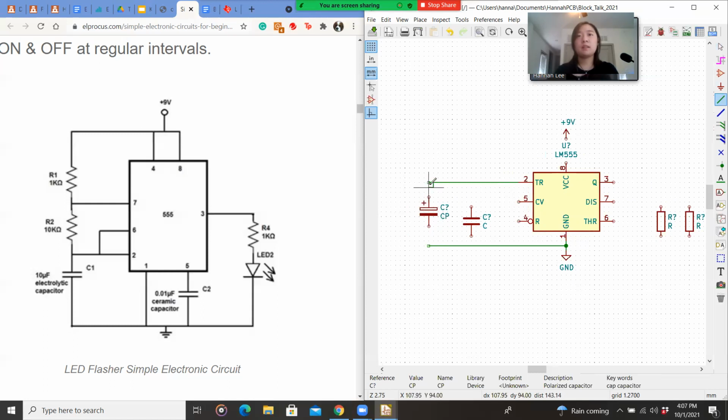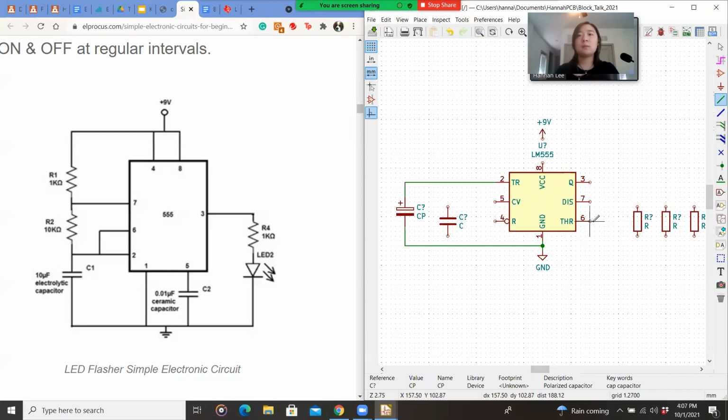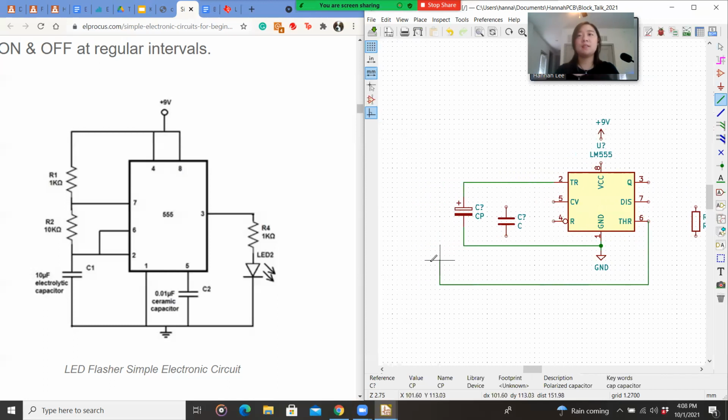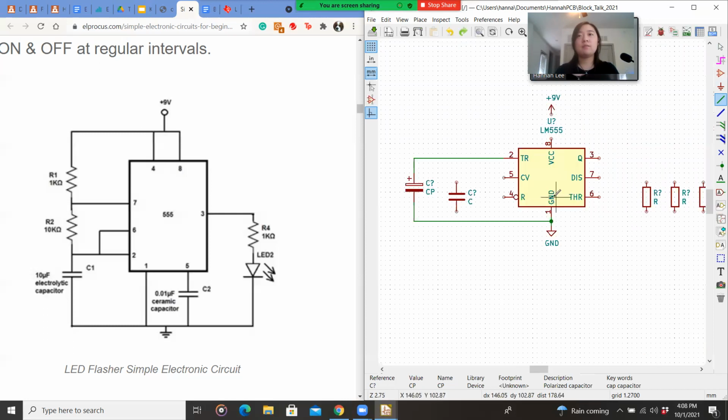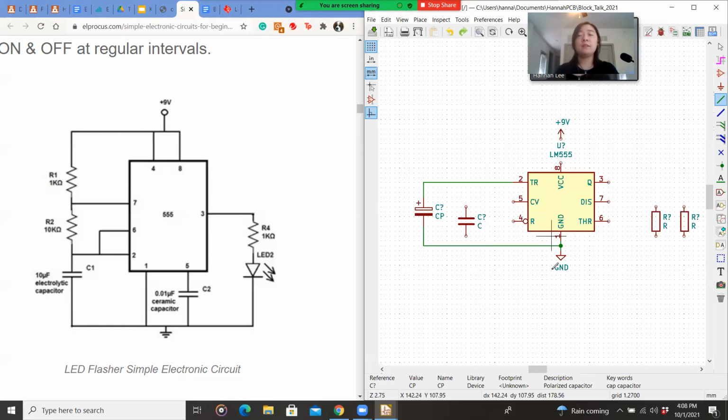Then go ahead and connect the dots to finish it here. Notice 2 is supposed to be connected to 6, but we'll come back to a way to make this easier to do, because this might be a little messy. Notice that this trace travels such a long distance, and if there are too many overlapping traces, it can get confusing and hard to read, which defeats the purpose of what we want the schematic to do. So we'll get back to maybe a different way to go about doing that.